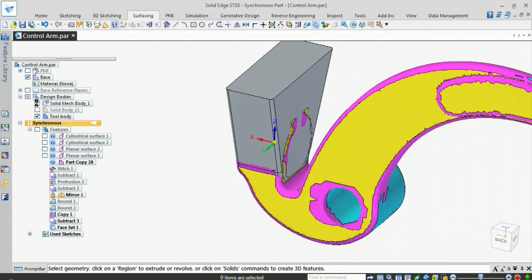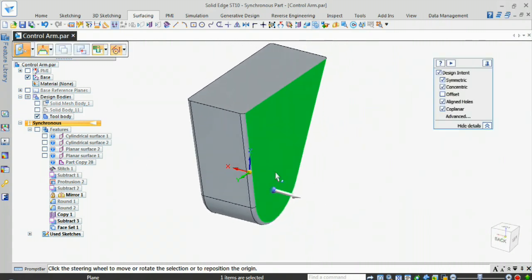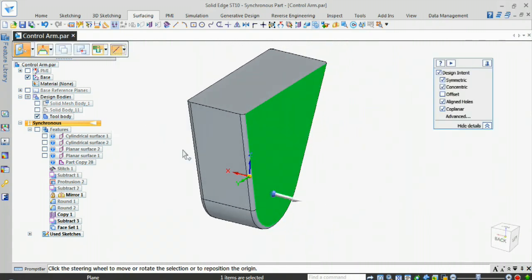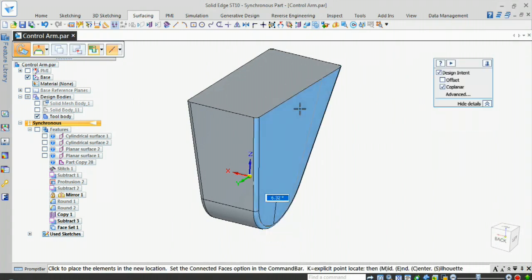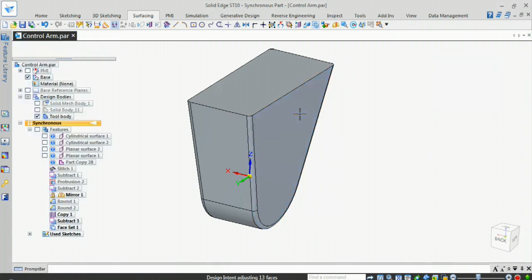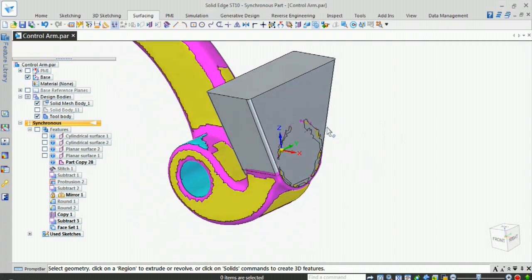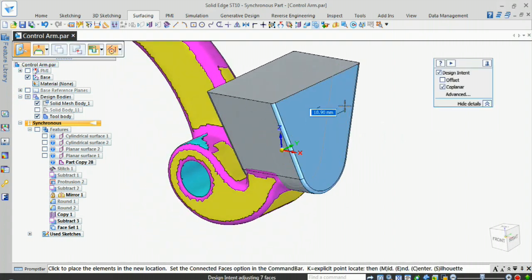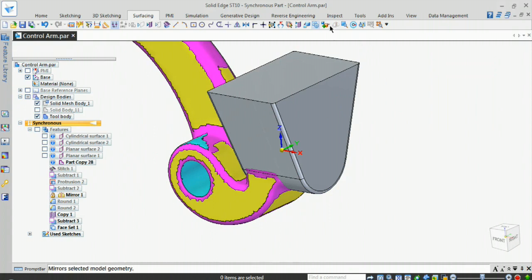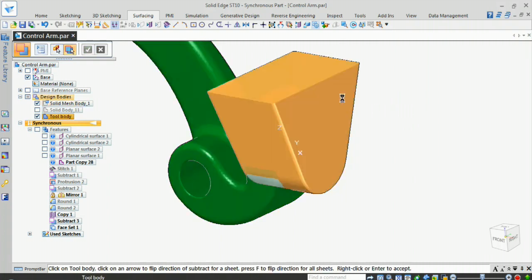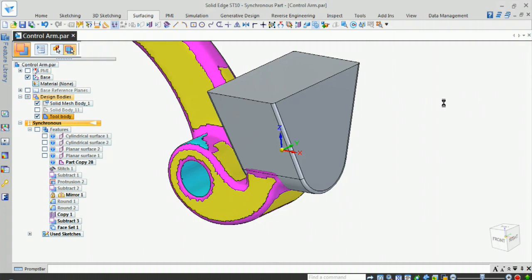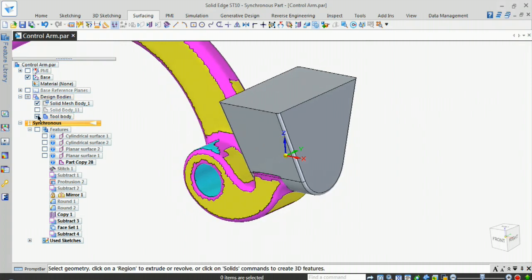Then we're going to change the angle on the back face to include all the geometry suitable for removal. And finally, we're going to extend the front face to make the whole body bigger. All of this is accomplished with Synchronous technology again. Finally, we can perform a Boolean operation, subtracting our tool geometry from the mesh. This is convergent modeling in action for you.